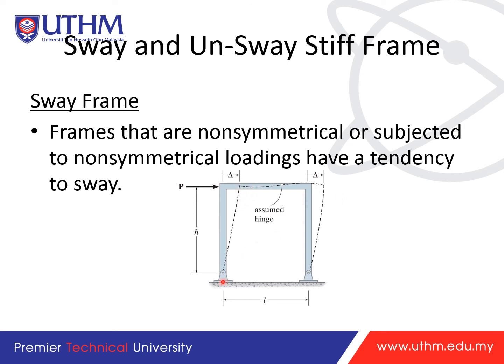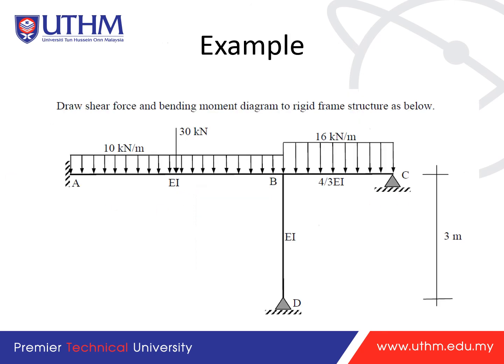When you are just roller supported, you can see that you have a sway. You will sway. You will move. When the load is applied towards the right, this frame will tend to move, and then it will cause a deflection. Okay, so this is a sway frame.